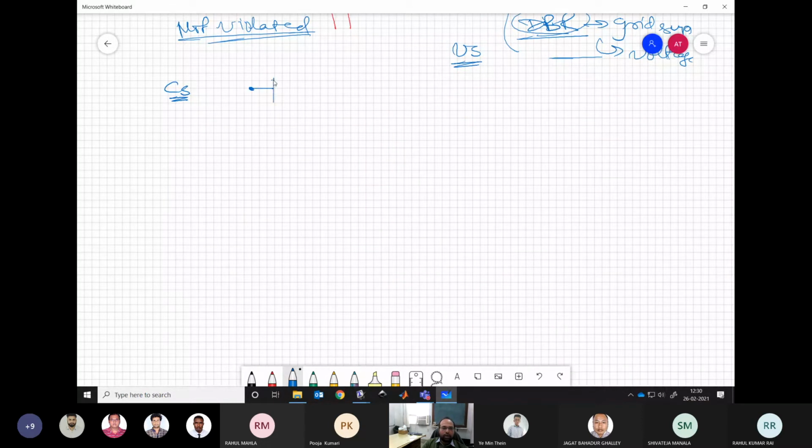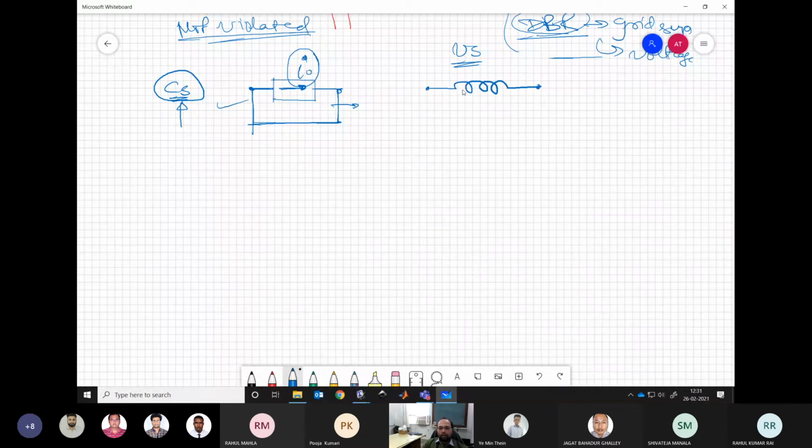By some arrangement, if I make the current in this circuit constant, let's say I naught, and there are no dissipative elements in this circuit, the current will keep on flowing forever. If you connect this to another circuit and somehow maintain this average value of current, this is as good as a current source. The nearest thing we can think of for this arrangement is an inductor.